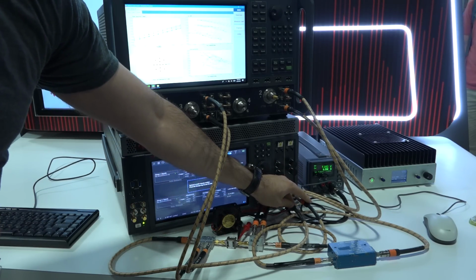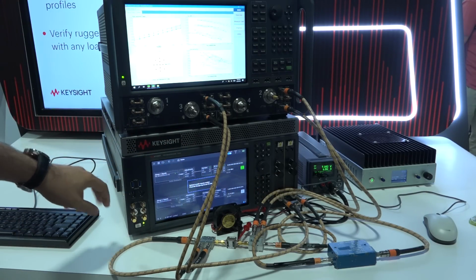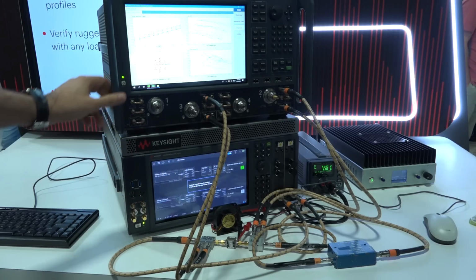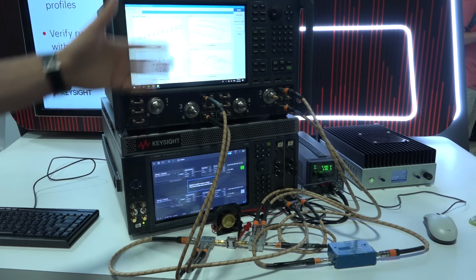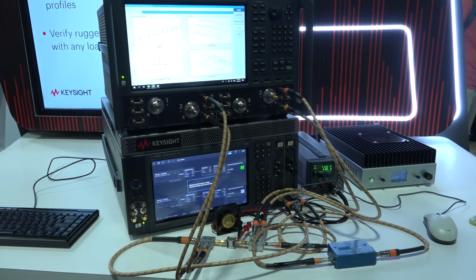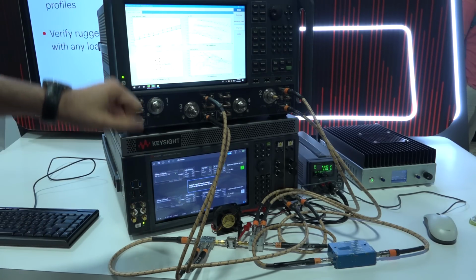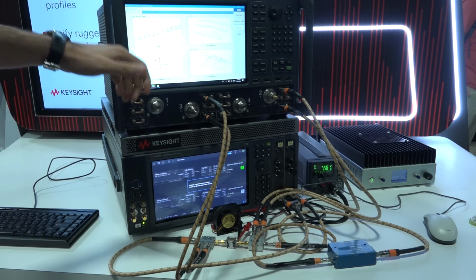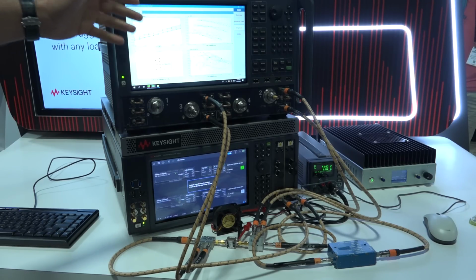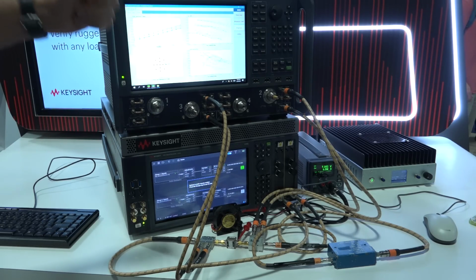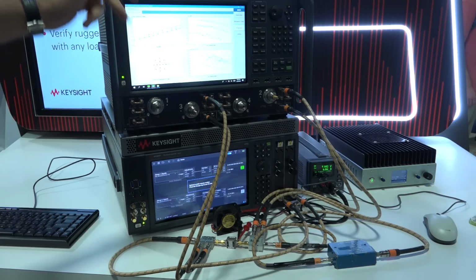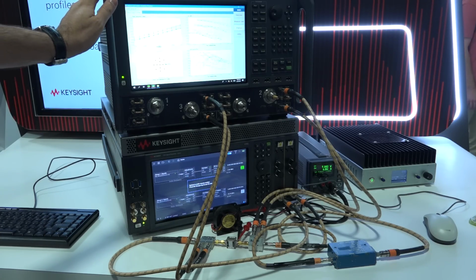We have broadband signals generated from both of the 2 channels of the VXG, going into the couplers and into your device under test. So now, once you have this set up together, there is a lot you can do. You can download profiles of the impedances you want to go through, but not only that, the PNA-X can actually do demodulation and perform EVM measurements too. So all of a sudden, you're going to get these curves, the curves of output power and frequency across the load pull circles that you actually want to cover.